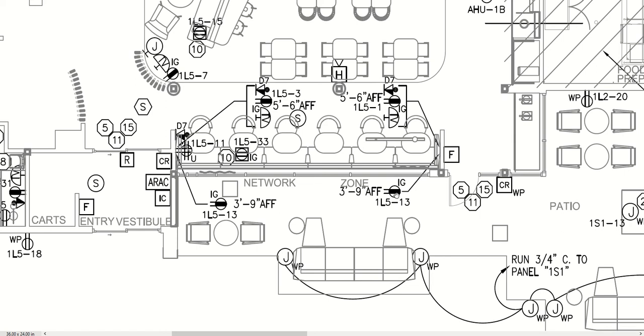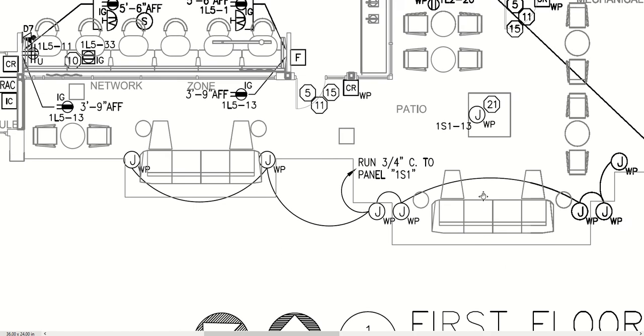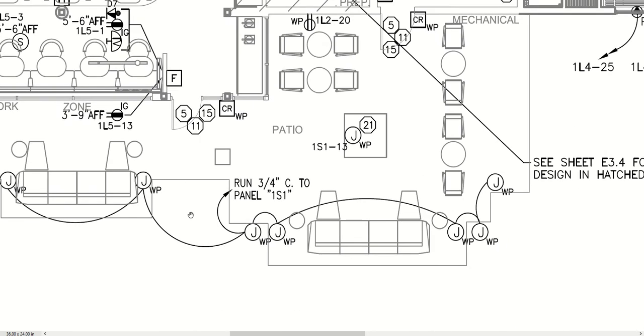And you can see these outlets are actually isolated ground outlets. We talked about that, and we'll see how that works on the riser diagram in a minute. And then here we have some connections for some outdoor equipment and lighting, and so we put weatherproof junction boxes out here and running all the power to that.